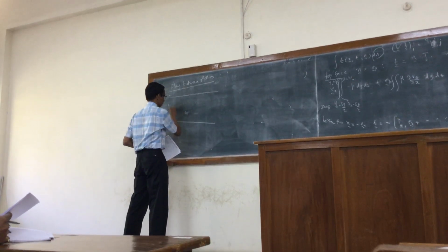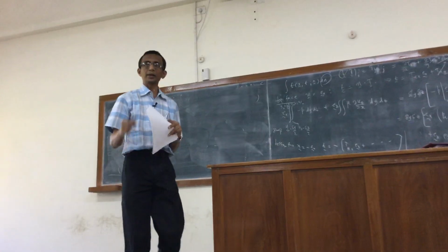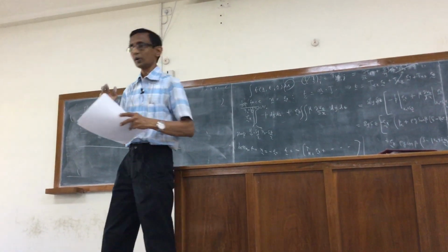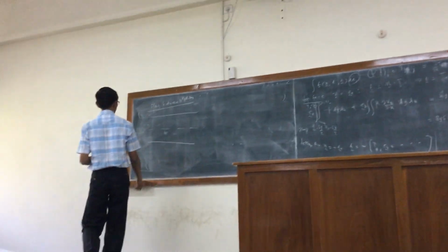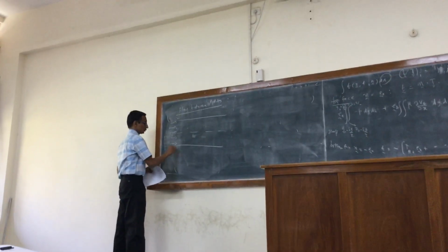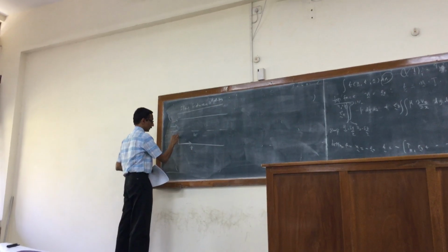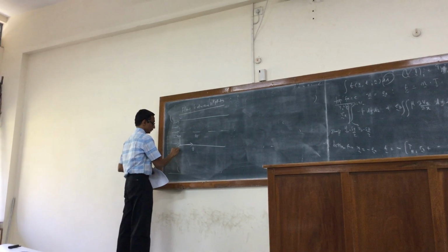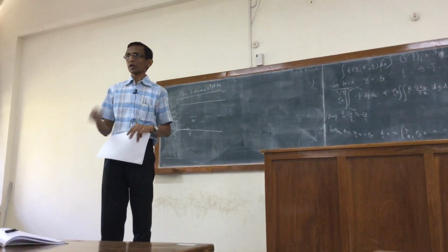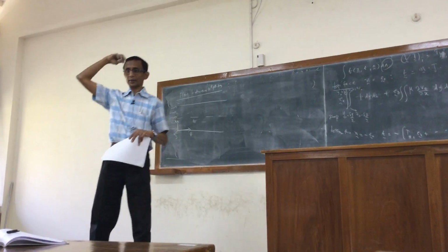So there are 2 plates here. The only complication that would arise is that typically we consider one of the plates to be moving, and so that will create some scope for analysis. Again, we assume a one-dimensional flow, and take this to be z, this to be x, and this to be y, so that the direction of flow is the same as what we had in the earlier case.